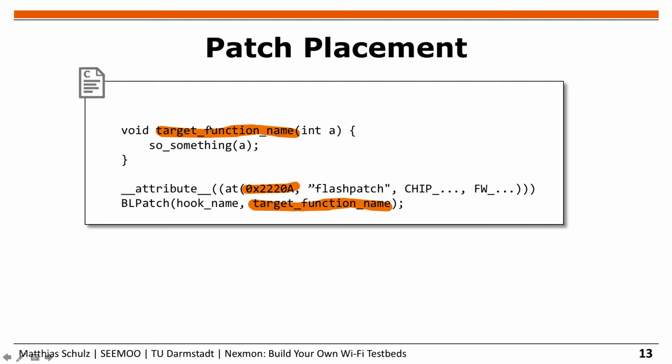So we simply decided we can collect all the functions that are not explicitly placed in a certain region, and the linker will put them at a certain place where we want them to be. Therefore we developed this special pragma target region and told it to place everything that is not explicitly placed in the patch region. Now, where do we place the patch region?